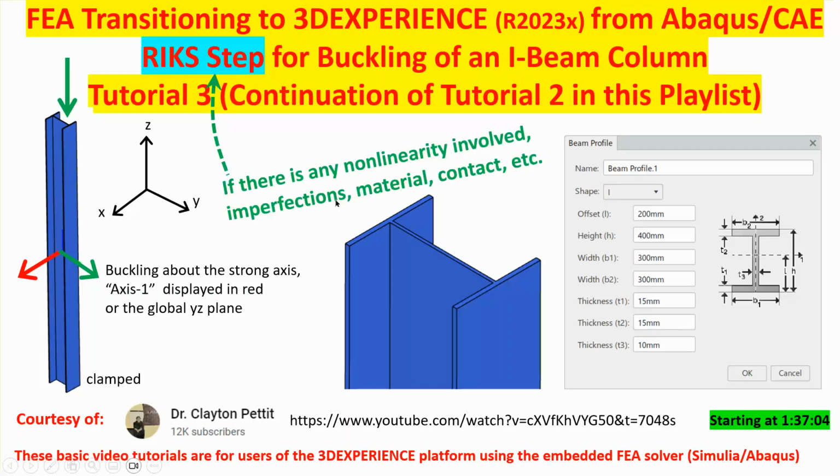So this is exactly what I said. In the present problem, we're going to assume there is no contact and there is no material nonlinearity. But let's say we didn't know these things. So what you want to do is go ahead and repeat that calculation with the RIKS method. However, keep in mind that the linear buckling analysis predicted a critical load of 7.4, I believe, 10 to the 6 Newton. Let's pretend we don't know that.